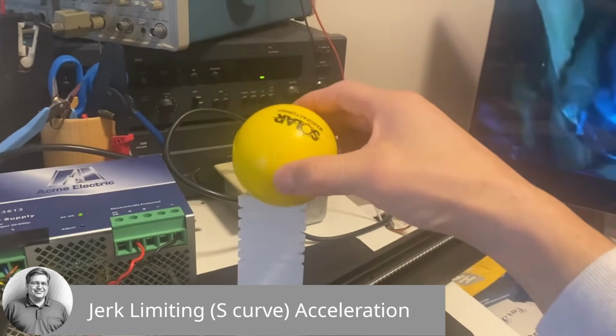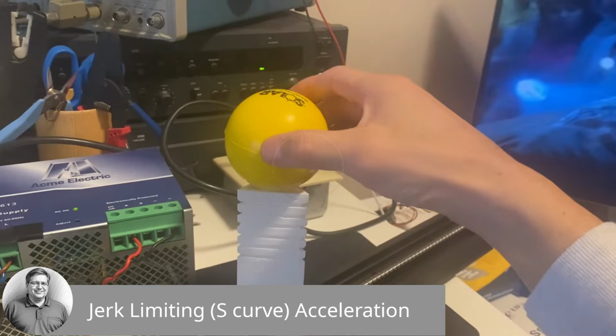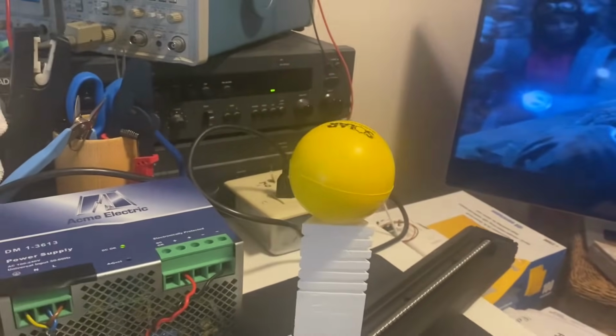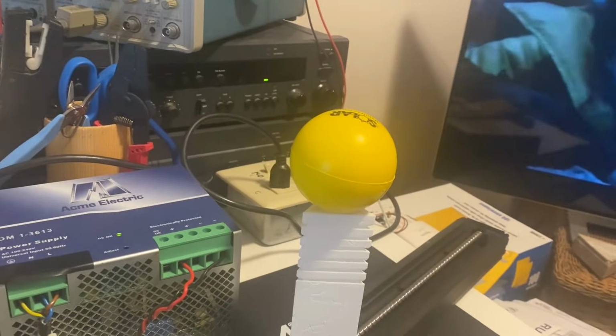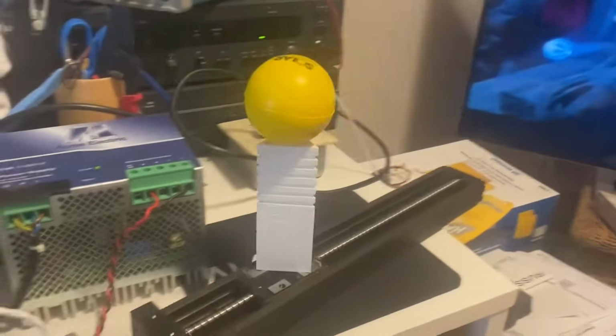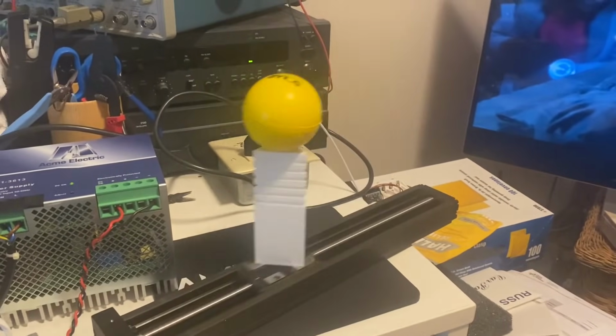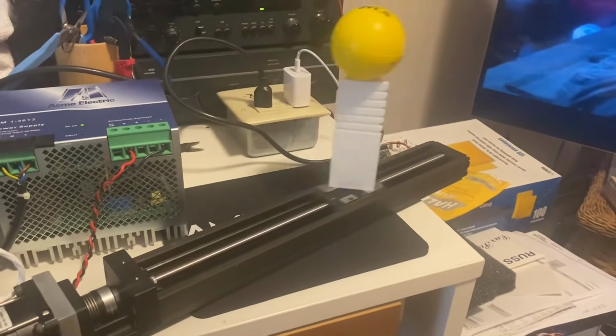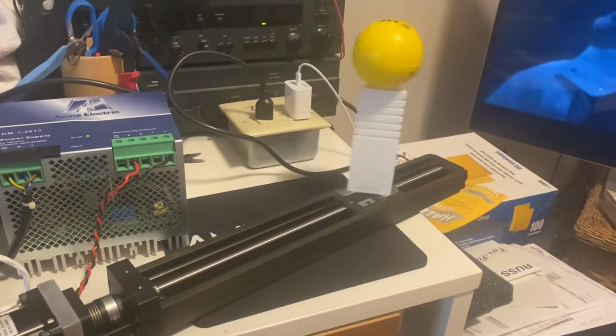In the CNC world, we are using a trapezoidal motion profile in LinuxCNC, and we call this infinite jerk. So we want smoother motion, and we need to vary our motion profile to look more like an S-curve. So as we come up to that corner, we decelerate a little bit within the timing constraints and negotiate around the corner without falling over. So for a CNC motion planner, this is extremely difficult to achieve.